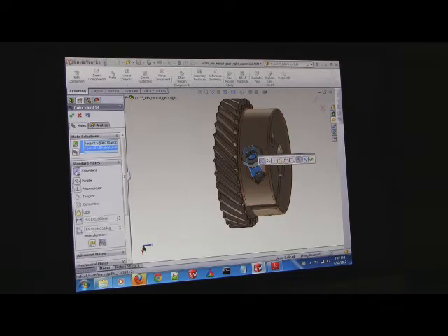Now, see how this says coincident? Very dangerous. Anybody know why? For 3D printed objects, we have tolerances. This hex hole is 5.5 millimeters. Now I happen to know that a 5.5 millimeter hole will be just perfect. But if for some reason I used a different surface finish and I had to have a 5 millimeter hole or a 4.6 millimeter hole instead, it would not do coincident because they couldn't be on top of each other. You don't want that. You want parallel. That's safer. That allows you to adjust the tolerances of the hole without actually hurting your mate. Now press the check mark.